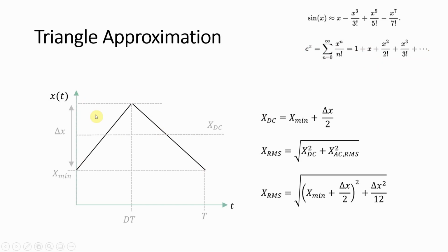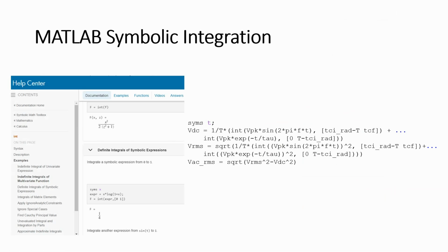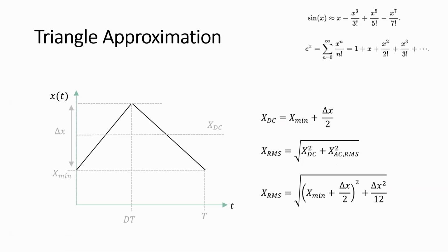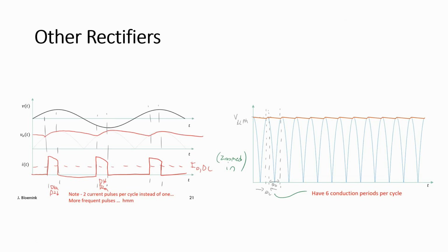And if you make that approximation, the charge and discharge would become a triangular behavior. And for a triangular waveform, or a sawtooth waveform, just like a periodic triangular waveform, we can find the DC and RMS values this easily. Okay, so these formulas are used in some textbooks for an RC circuit. This is an approximation. It doesn't matter if you want to use the approximations or the actual formula from the MATLAB simulation, but this one is sometimes easier.